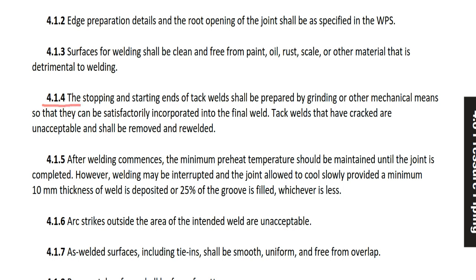4.1.4 The stopping and starting ends of tack welds should be prepared by grinding or other mechanical means so that they can be satisfactorily incorporated into the final weld. Tack welds that have cracked are unacceptable and should be removed and rewelded.